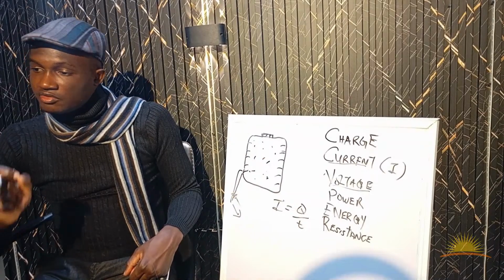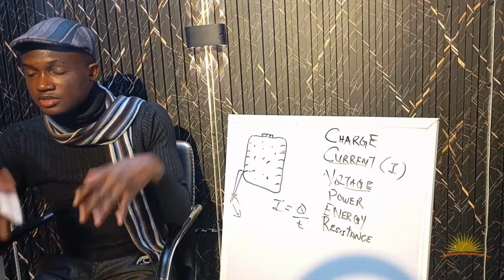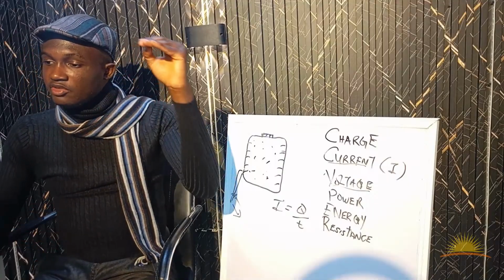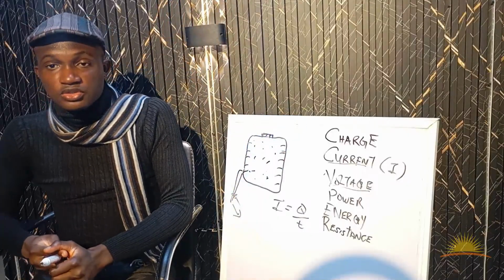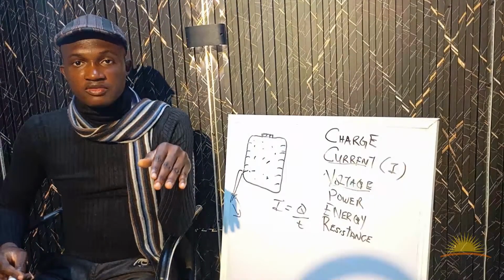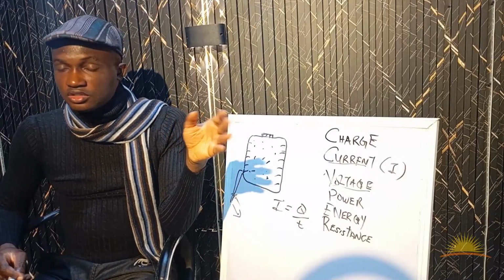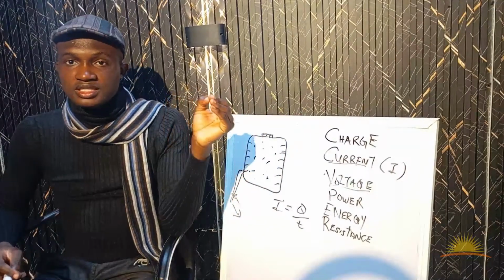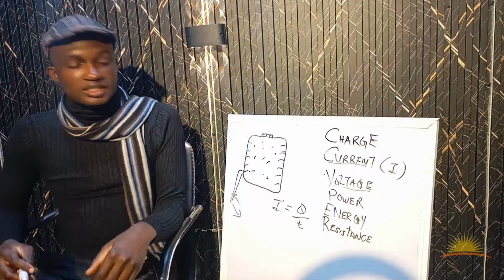When the voltage value of a battery is low, we say the battery is low, because voltage is not something that's inside the battery, it is a value. And when the voltage reaches a particular value, we say it is high. For example, the battery we usually use in solar engineering, the lead acid battery, has a low voltage level of 11 and a high voltage level of 14. Lithium has 12.6 for the high and the low is 10.5. So depending on the battery, you have a high level and a low level voltage.